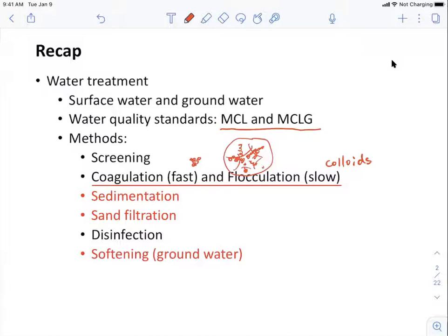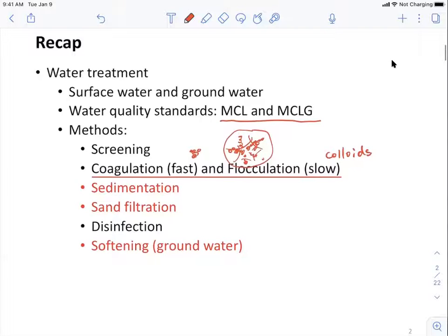So that's why we use a slower turbine, right? We use paddles that have very small velocities, or very peaceful rotation, or we just don't use any paddle at all. We just use channels, to let the water go by itself. After a sufficiently long suspension time, we can remove these contaminants.